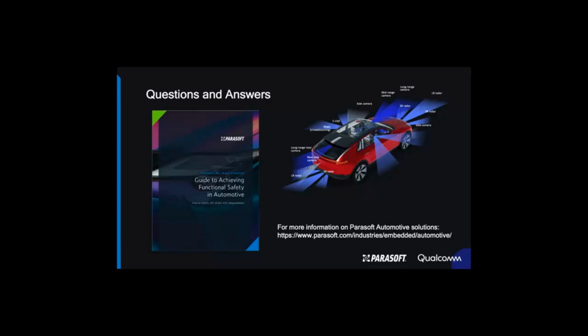As Guru just pointed out, one of the things that was really important for the assessor is having strong evidence. And being able to collect that evidence means you have the capability to perform the types of testing and get that data in a useful format that the assessor can see, navigate, and understand. For ASIL D, for example, you have to do MC/DC coverage, and you have to be able to collect that code coverage on target. These are really complex things to do for an embedded system.